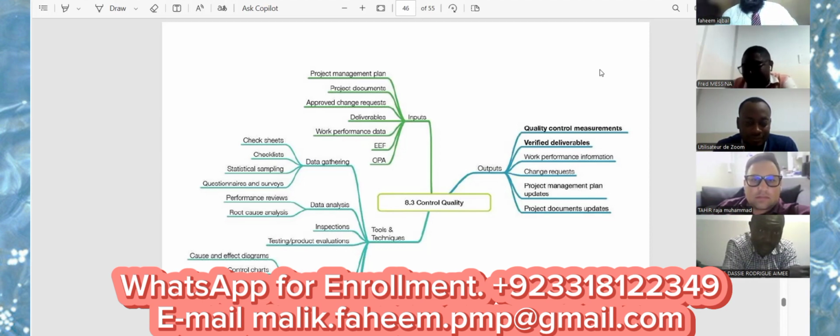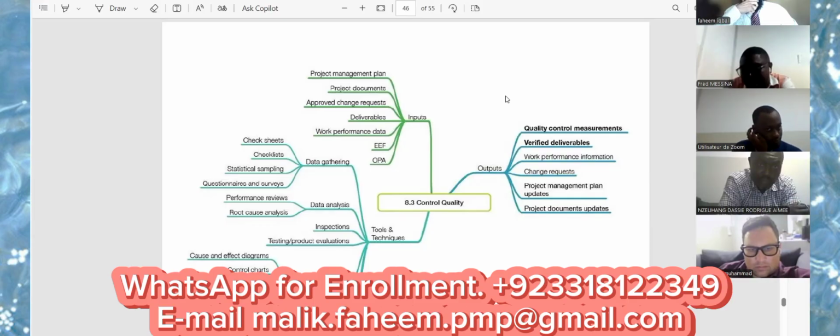Yes, sir. I was saying that what you're explaining is like what we send to the third party, which is called a coupon. The statistical data analysis Mr. Tahir was talking about, we gather it like the coupon test. We check one of our joints, a certain percentage of the work. If it is okay, then we will consider the rest of the joints also okay. If a joint is rejected, then we will take 2 more joints. There is a normal repair procedure. You should follow the repair procedure. It should be written in the repair procedure. Mr. Tahir knows very well.